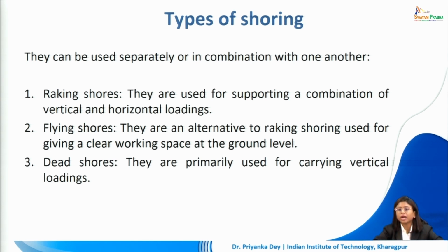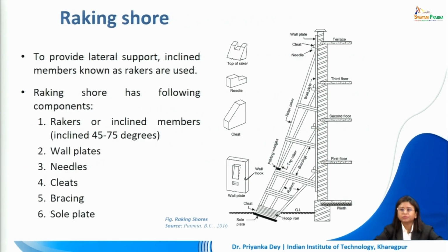Dead shores are primarily used for carrying vertical loadings. So let's say we are creating an opening in a wall and we want to give support to the portion above the opening, we can go for dead shores. So let's dive a little bit more in detail into each of these types.